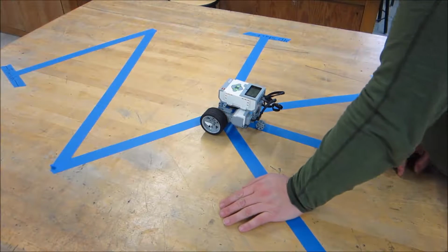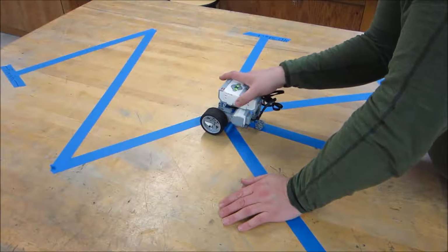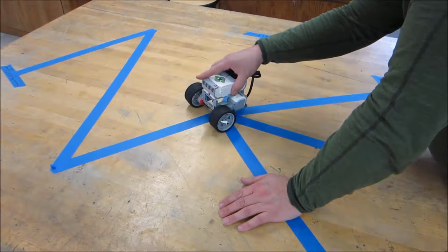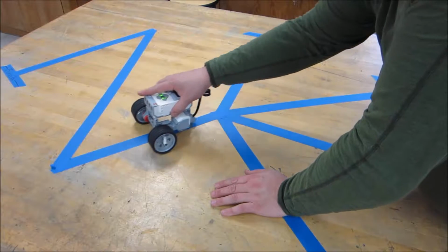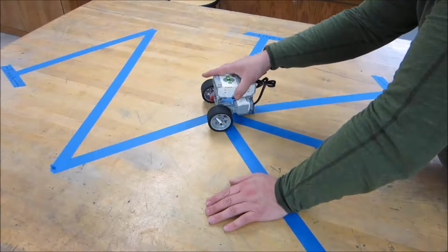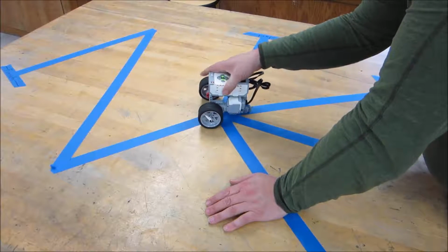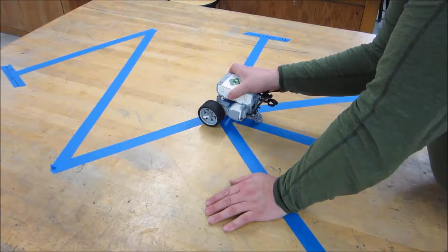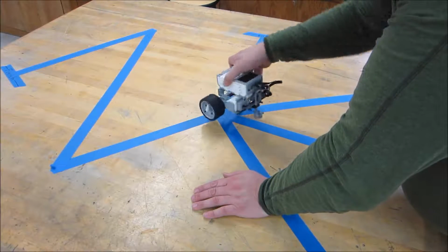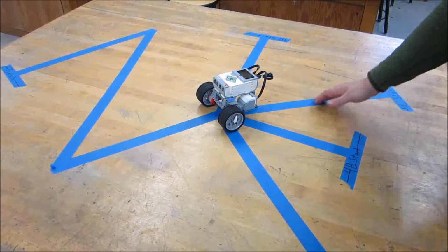Now what we have to do is we have to program it. We're going to wait a second for it to settle so we get more accurate movement. Then we're going to have it turn. If I do the turn exactly right, the robot will end up here facing the exact direction of this second line. If I do too much, if I put too many seconds, it's going to go past that. If I do too little of a turn, it's going to go here and not go enough. So we're going to turn, but remember what we're not going to do is make slow arcing turns. We're going to make a turn where it turns all together in place. And we want it to face perfectly in this direction.